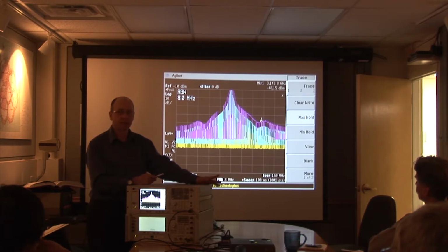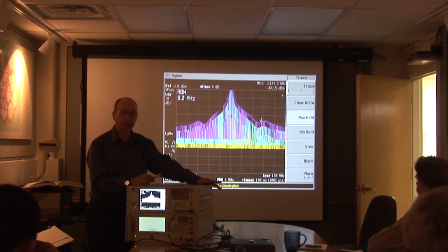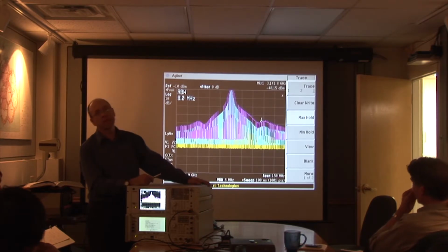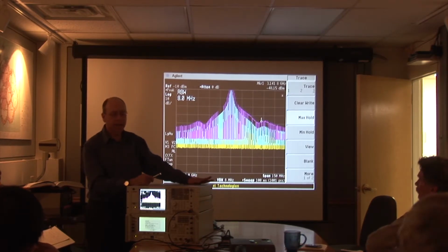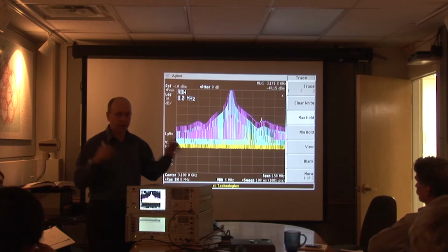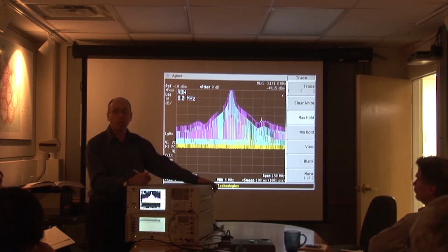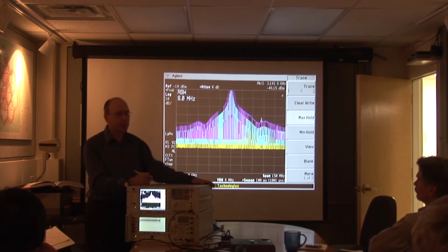So it replicates this sort of typical medium to long range air traffic control radar, air search radar, and so it has a 0.1% duty cycle. And just to make it easy, we decided to make our radar, in quotes, pulse itself on and off once every second. So this would represent a radar that's rotating really, really fast.